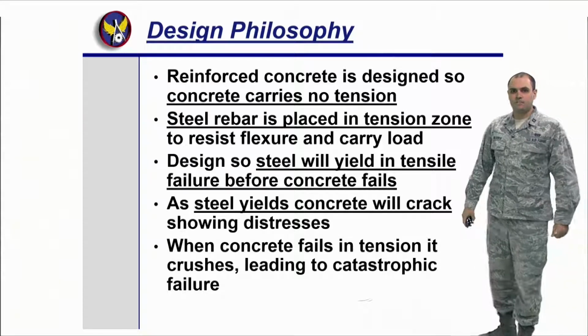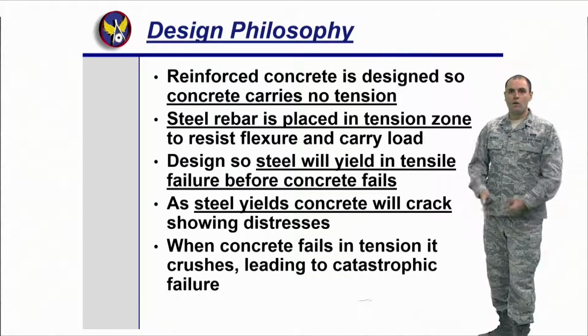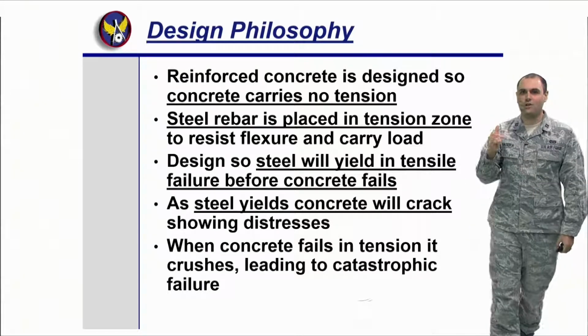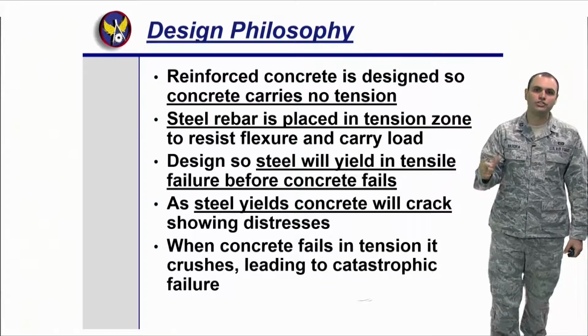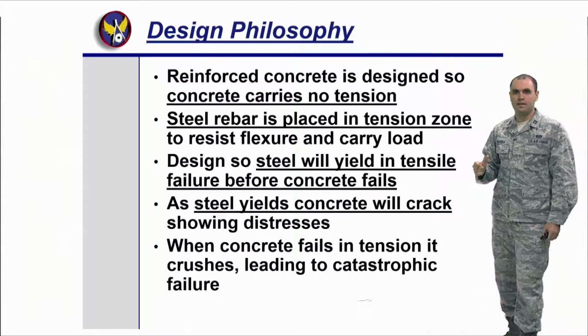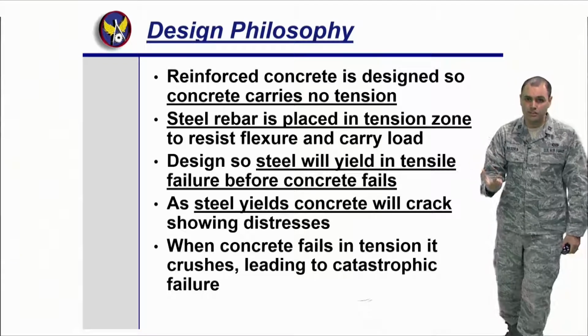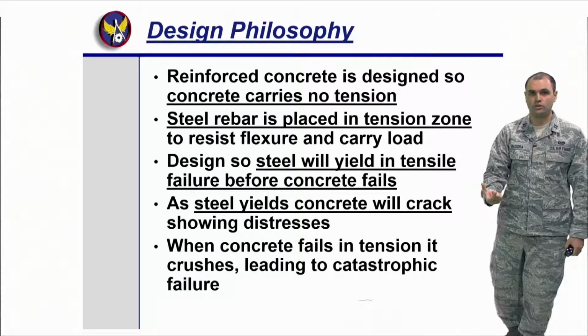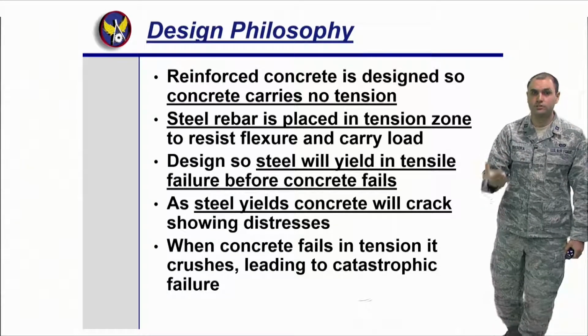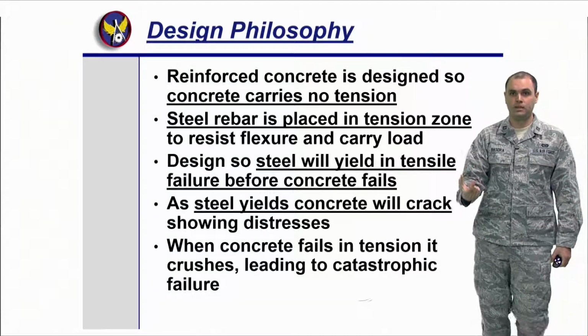Design philosophy. Like I said with the Whitney stress block, once we go past that neutral axis, the concrete is doing nothing. All the tension is being carried by the steel, right? Therefore, we're going to place the steel rebar in the tension zone to resist flexure and carry the load.